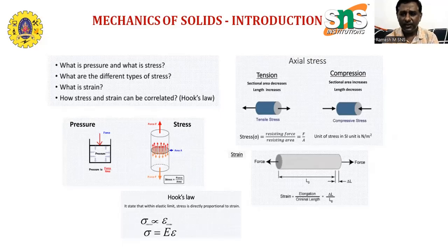One chair is used for sitting for one man. But while designing, they make the factor of safety three instead of one. For one person, consider the maximum weight to be 80 kilograms. If the factor of safety is 3, that means 3 times the weight of one person, that is 3 into 80, 240 kilograms is the maximum weight. That is the ultimate weight.